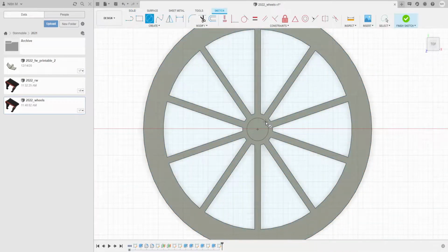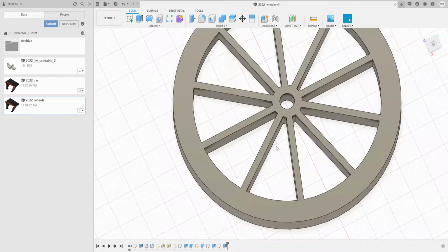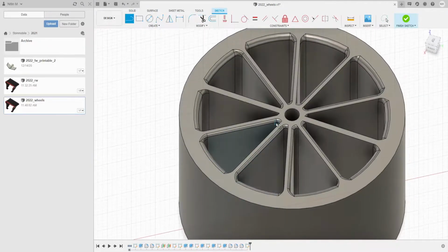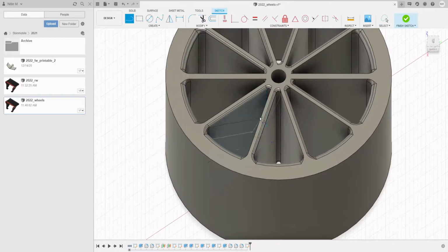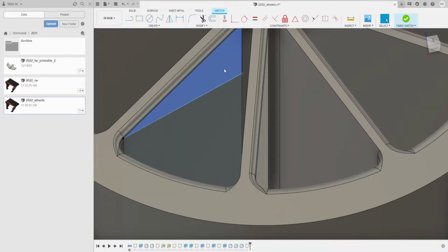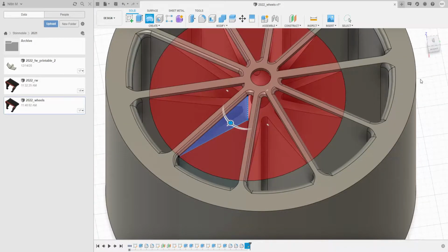I added a 3mm hole that runs down the length of the rim and filleted the edges of the spokes. I then got around to profiling the outside of the rim by adding a triangular sketch to one of the spokes and using the revolve tool to cut the spokes. But oddly enough, it seemed that the cut was off-center.